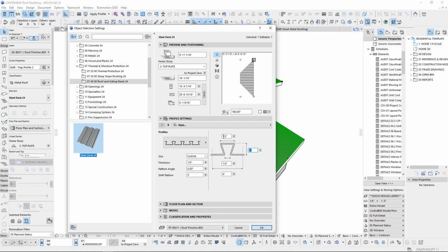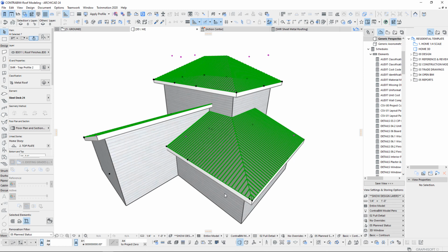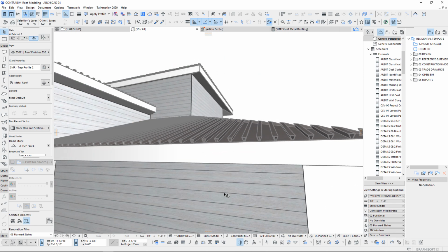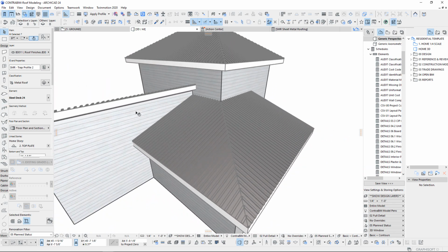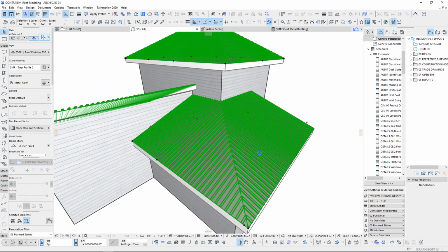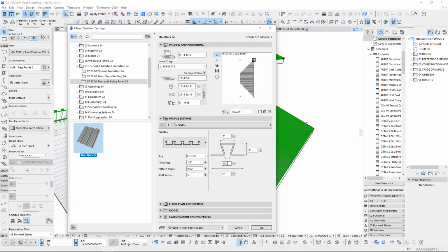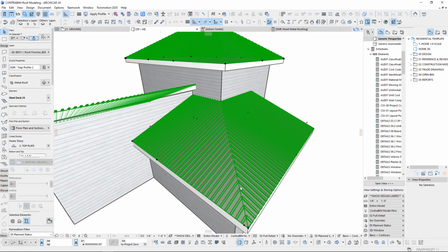distance. If we take this to say 2 inches wide, if we left this here, it would give us some really strange trapezoid type shapes. That definitely looks interesting though. If we want to make them just wider, if this is 1/8 inch, then if we set this to say 1.75 inches, it should give us a pretty straight section cutting through there.